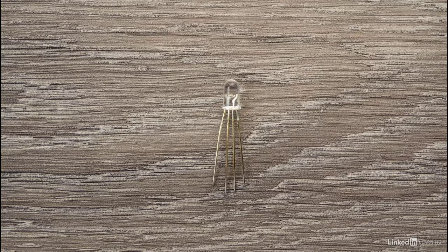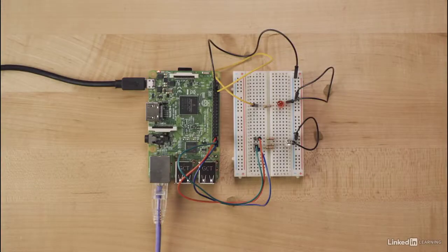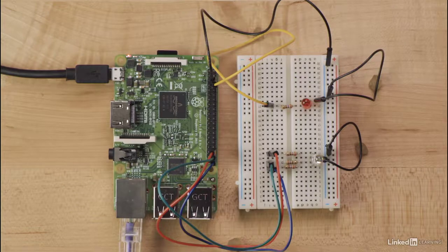The 3 other leads on the RGB LED are for red, green, and blue colors in the LED. Connect the RGB leads through the 270 ohm resistors to the Raspberry Pi as shown in the handout. When you're finished, you'll have 4 wires from the Raspberry Pi to LED legs, plus 1 ground wire from the Raspberry Pi to the breadboard ground.